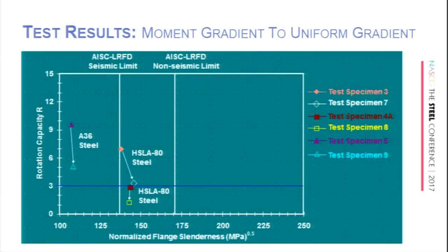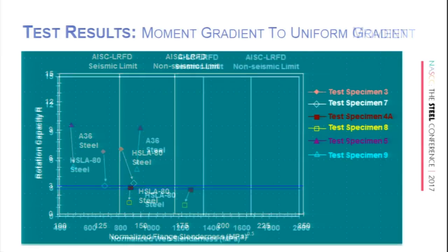And again, here's a comparison with A36 steel members and then with my HSLA members. Okay. Some of the takeaways here are about what rotation capacity I need if I was doing a monotonic test. It's probably almost on the order of 3 times that. If I had a rotation capacity of 8 or 9, more than likely, I'm in a seismic or cyclic type testing where that rotation capacity of 3 means something. And we've done this. We've taken our curves and the cyclic curves and literally fit over, like a backbone curve, the monotonic test over the cyclic test to see all this behavior.